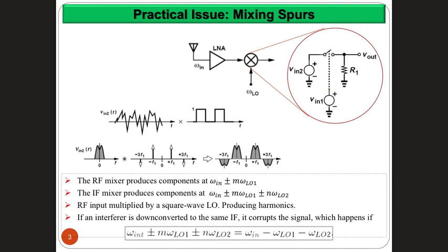Yes. The one that has two inputs, and the finding we eventually found was that the output of this is somehow the multiplication of those two signals together. One of the signals is controlling switching on and off, and the other one is put as an input to the system. The output that you will get from here is going to be something like multiplying those two signals together. Okay? That's basically what a mixer is doing, multiplying two signals together in an analog form.